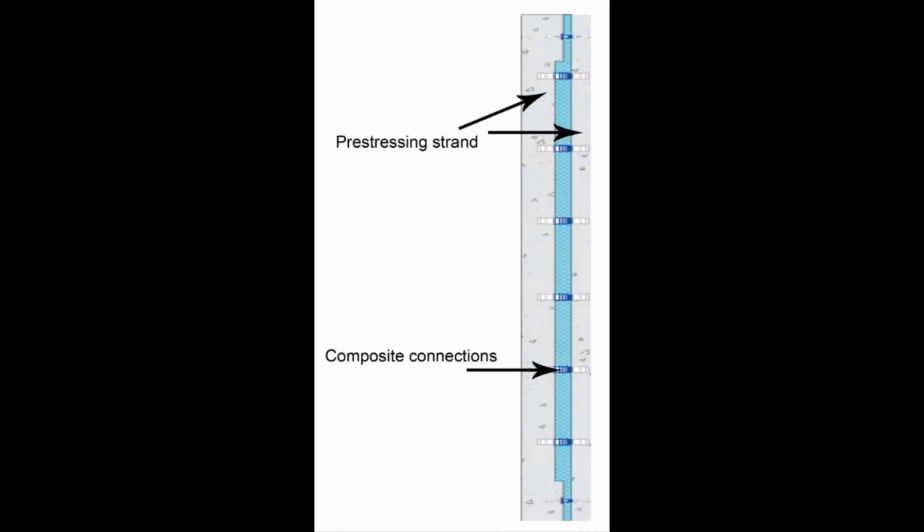Fully composite panels: the withes act together as a unit for horizontal and shear transfer. A typical composite panel is 8 times stiffer, can take 3 times the stress without cracking, and has twice the ultimate strength of a non-composite panel of similar thickness. Composite panels are typically less expensive than non-composite panels, primarily because they can carry more load and can be made taller and thinner. The inside and outside withes are usually stressed with pre-stressing strand and made of equal thicknesses in order to minimize internal strains.